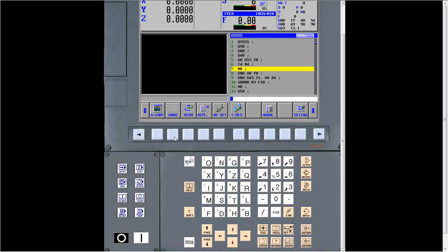So how about engraving on that same kind of machine? Yes. Engraving is totally possible, because Mark, obviously, if you have a live tool lathe, there's different configurations of live tool lathes. You can have one where there's 3 axes, where you have X, Z, and then the C axis on the spindle, where you're going to be doing polar coordinate programming. So yes, you can do engraving that way. And then you can have a mill turn machine where it's got a Y-axis. And then it's going to be more like a mill lathe. So you can do it both ways. So yes, you can do engraving also.